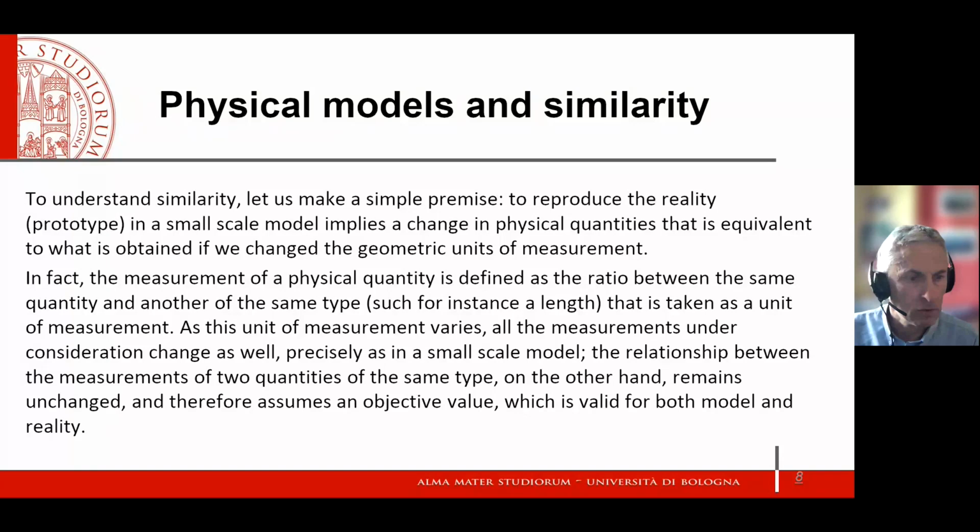When we reproduce the reality, a prototype, in a small scale model, we have to make sure that dimensionless quantities are preserved. This is the way we check similarity. And it is very, very smart, I would say. This consideration helps us a lot. It provides a firm criterion to assess whether the model is similar to reality.